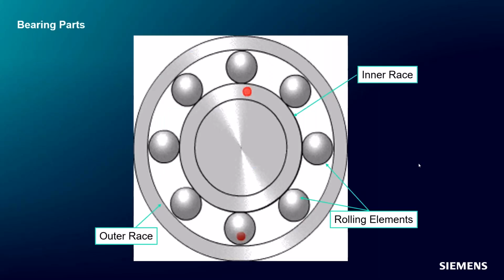If you look at all these bearings, they have some common elements. There's a thing called the inner race, and that goes around the shaft that is rotating. Then you have these rolling elements, whether they're ball bearings or rollers or whatever they happen to be. And then there's an outer race that's attached to the piece of machinery that the shaft is spinning in. So inner race, outer race, and rolling elements. And as a bearing's operating, Steph, it might produce some vibration, right? And orders are a vibration that is proportional to the speed at which the equipment is operating.